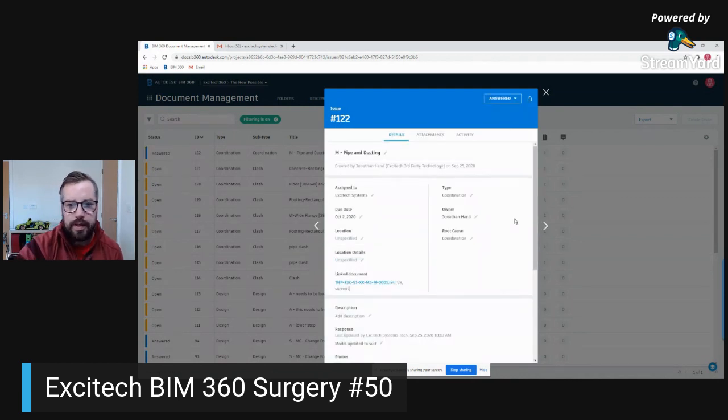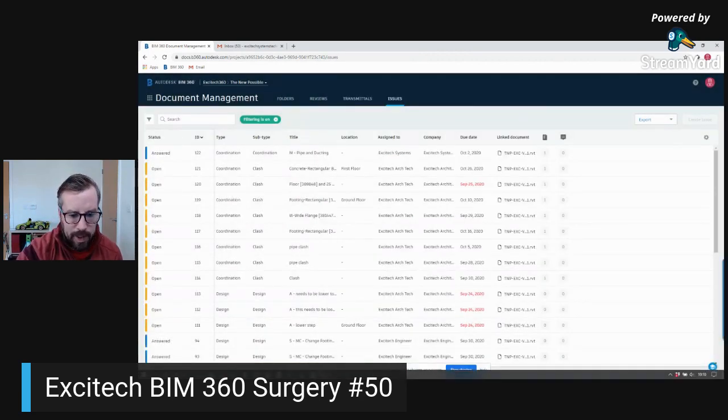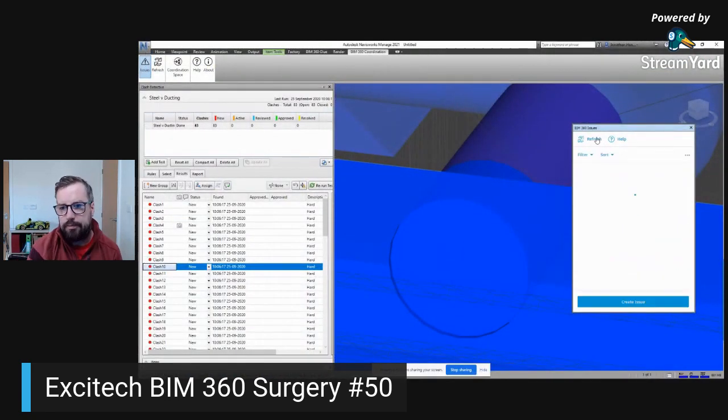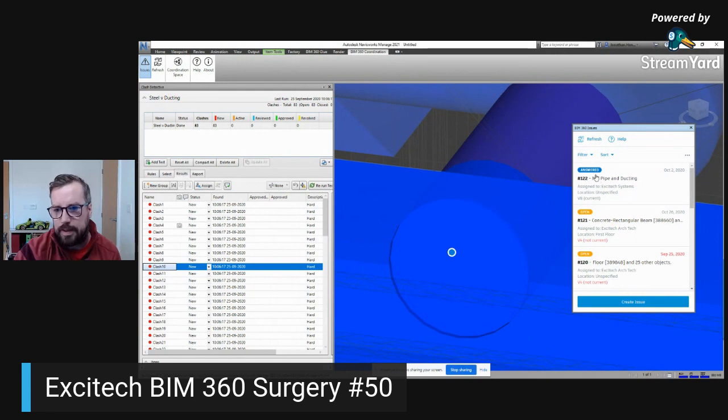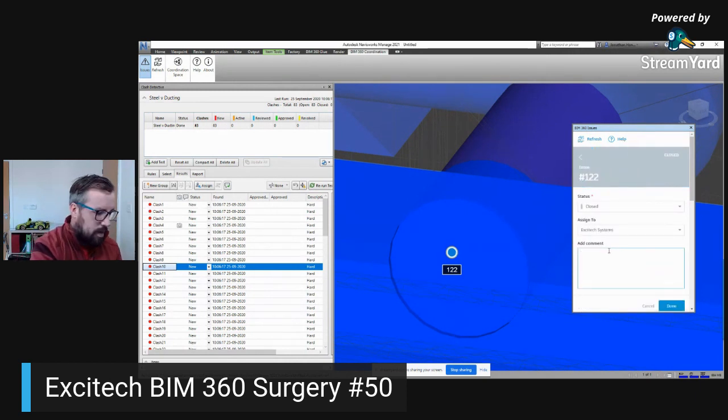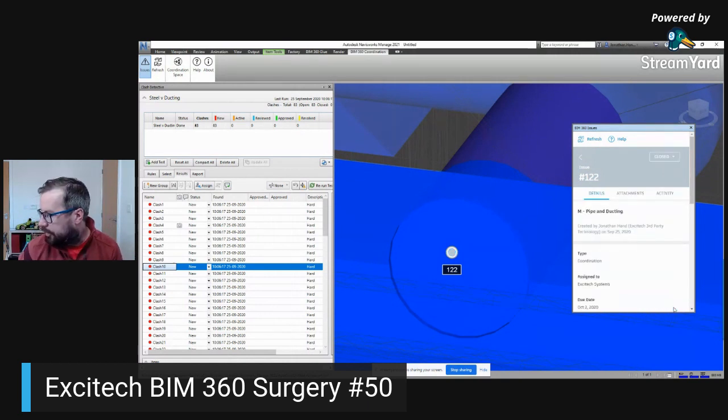So now the issue was raised in Navis. It's round tripped into 360. I've answered it and then assigned it back to my team lead. And if we click back into Navisworks, quick refresh, obviously then you can see this issue is now answered. And because I'm the guy who raised it, I can then close it. Thanks for updating. We are all done.